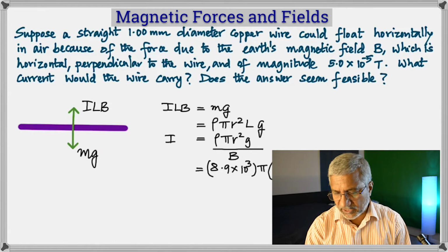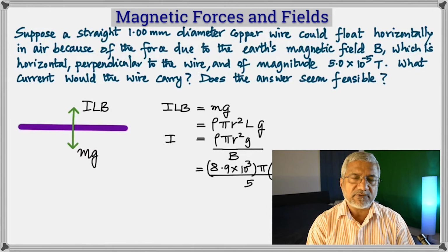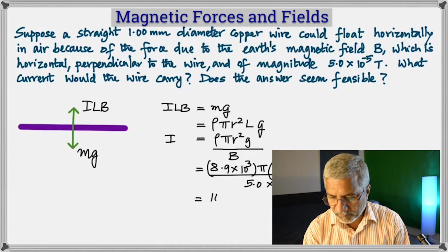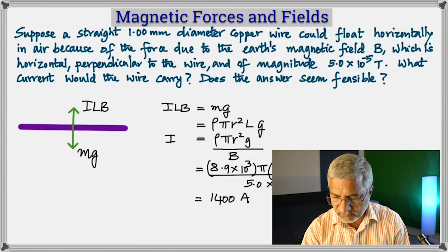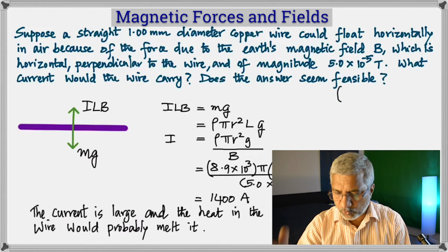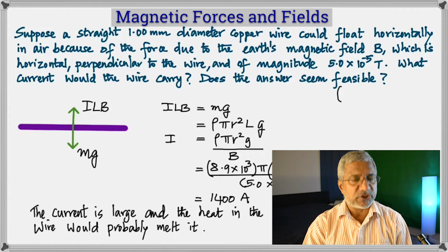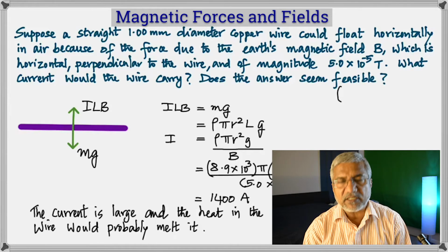Be careful with that. If you don't remember it there, you can just divide it by 4 because you're squaring it, remember. See if I do that. So 1 times... did I? Okay, let's find out. Times 980. That is diameter, and I used it as the radius. Oh, now I did it. Okay, I did it. I didn't catch it initially. You saw that. But then I divided by 4, and then I calculated, and the current is what? 1400 ampere.